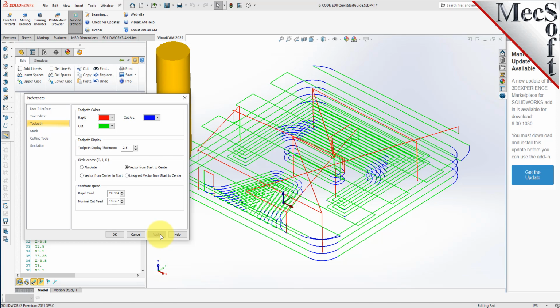That's an extensive change. So we're just matching what's in the G-code file so that they display properly. If you see this on your controller, you need to go back into the CAM module and adjust your IJK format settings in the post-process generator to match what your machine controller is expecting to see. Okay, let's continue.